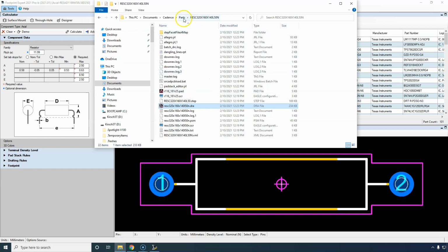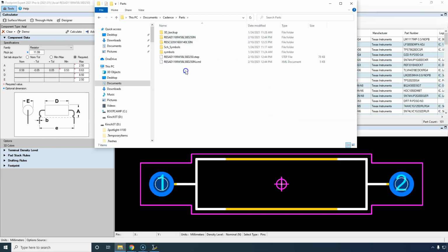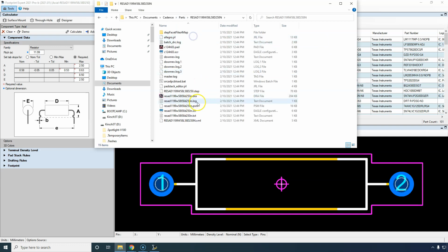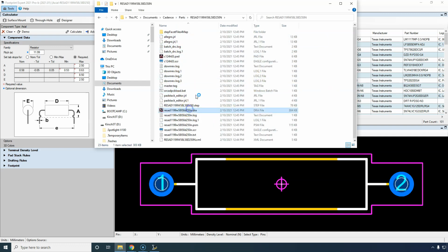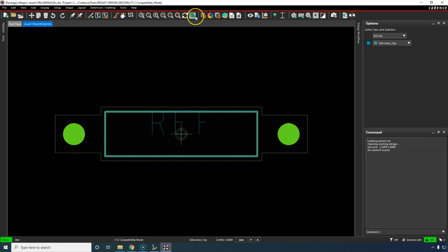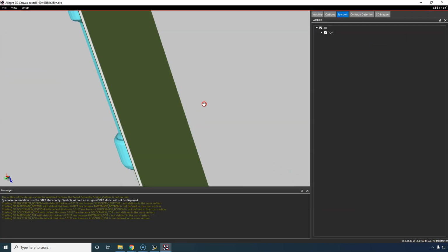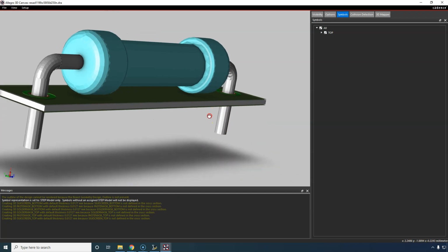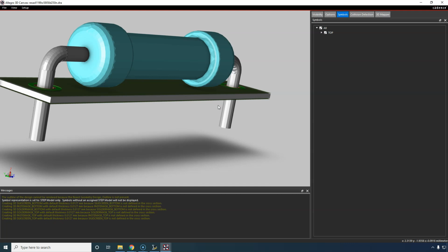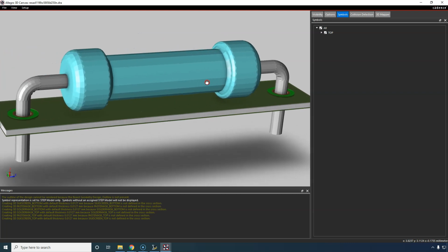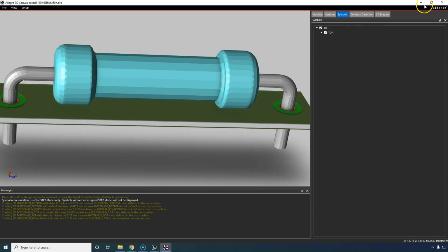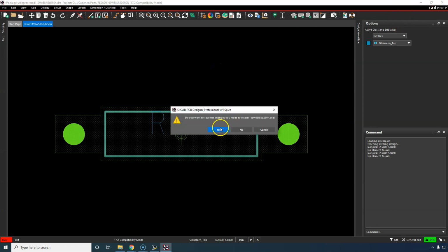Let's go to the footprint that was created with the script. I'm going to move these components in here. I don't think I have to do that, but I just do it each time. Great. Now if we open up the footprint in PCB Editor, let's take a look at it. Beautiful 3D view. Click OK. All right, look at that. And it also cuts off the leads so they're not super long leads, like when you download them from a third party, like 3D ContentCentral or GrabCAD. Man, just fantastic. Go ahead, close that, click save, yes.